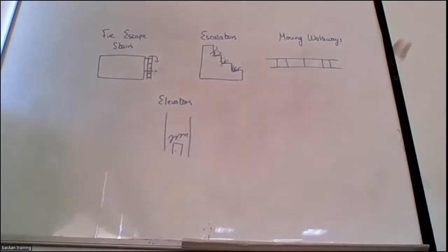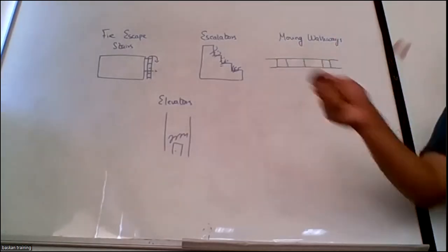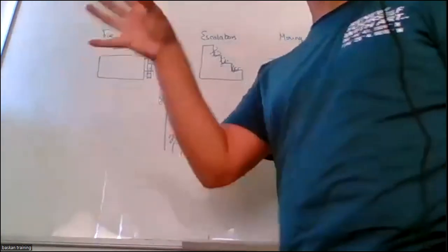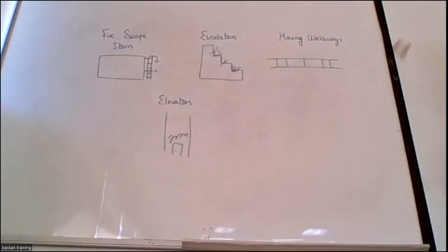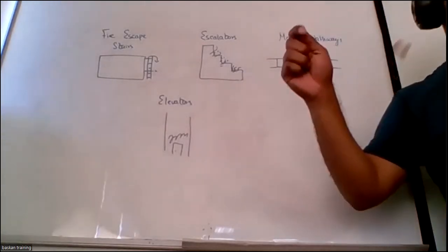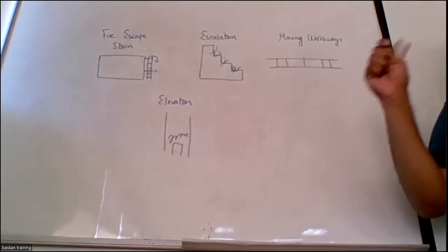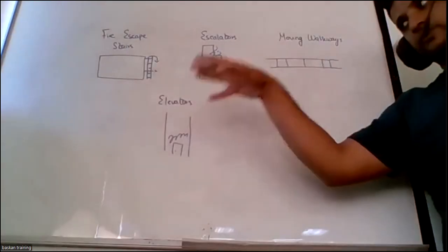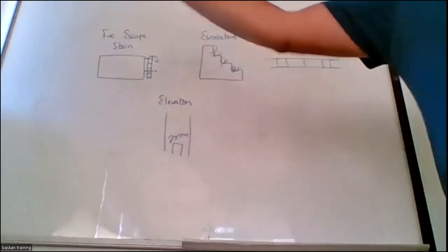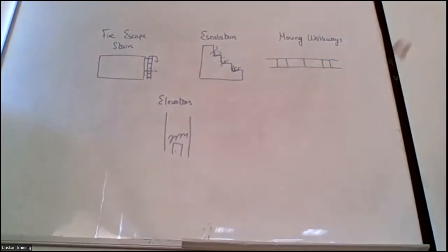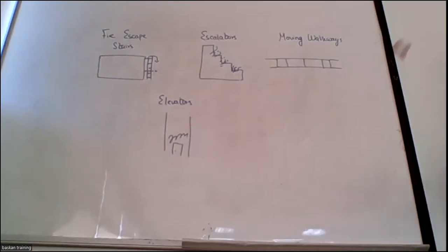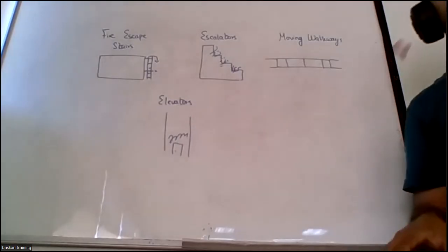Okay, so any component that is actually separating you from the building means that you open the door, you open the window, you move out. So that door and that window, that material itself is the exit. But exit discharge is the position that is completely isolating yourself outside of the building, in the public pathway. Either it's on the footpath, on the street, across the street, but you are in the public. It means you are not nearby any component of the building. So that is the exit discharge.